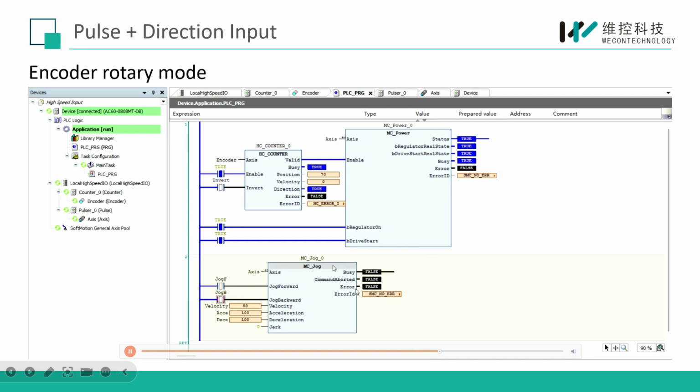And this is another direction. It will reduce to 0 and begin from 360 and reduce to 0 again. Just a different direction. And also for this HC counter, you can see here this invert input terminal. This terminal is used to change the counting direction.